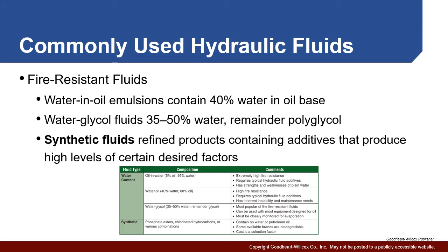There are a variety of different synthetic fluids out there made with things like esters and hydrocarbons that are designed to resist fire as well. We can do this with certain additives, and in general they have a number of the desired factors that we want. But keep in mind, synthetic fluids are significantly more expensive, and oftentimes, if you can avoid it, you try to work with your standard hydraulic fluids, because all of these have trade-offs. They're definitely not as functional as petroleum-based hydraulic fluid.